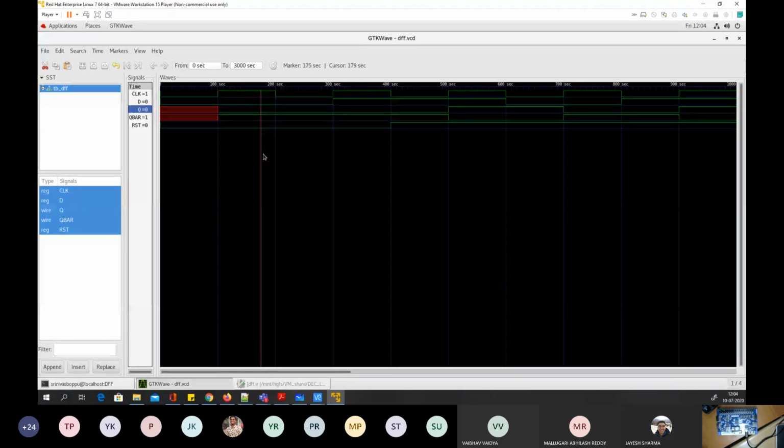Now, why is the signal red here? In general, let me tell you one thing. When you open any simulation, if you see something red, not in the beginning but in between, then something is wrong with your design. By looking at the colors alone we can tell. But in the beginning, before the reset becomes inactive, it's okay to have some undefined signal; in between, we shouldn't.